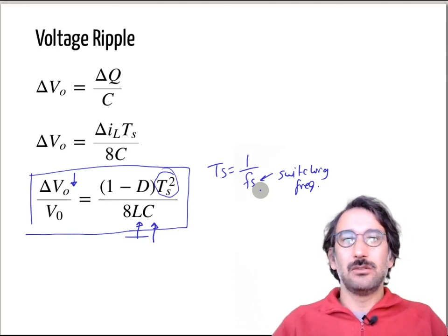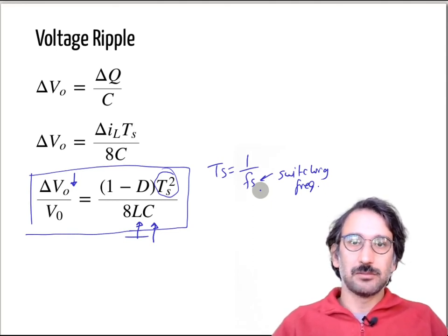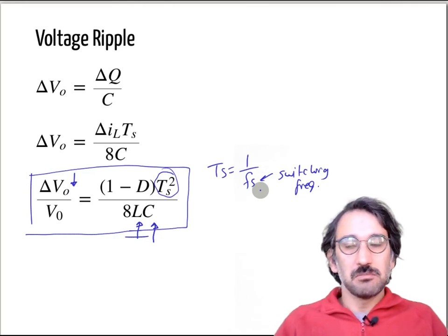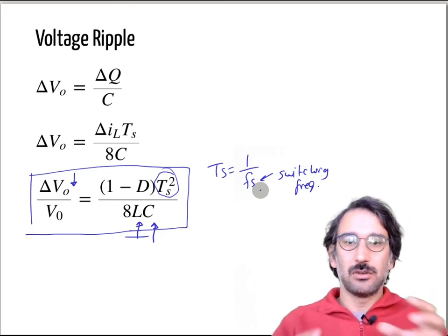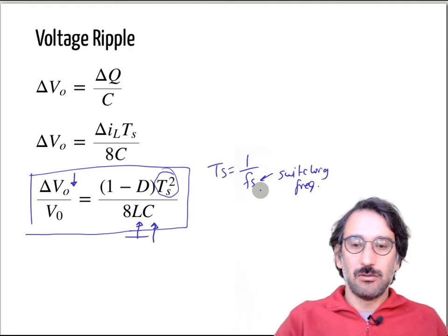Or you can use much higher switching frequency devices, but they also increase the cost. If you can manage to dissipate the heat, you can get a smaller converter size.